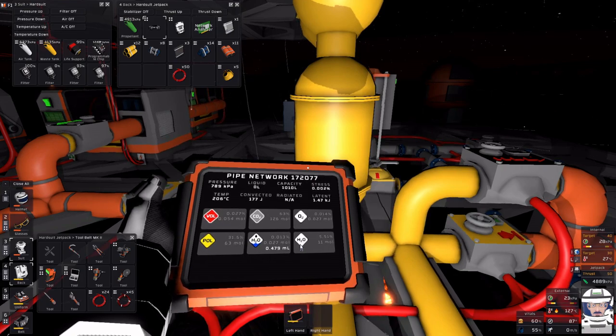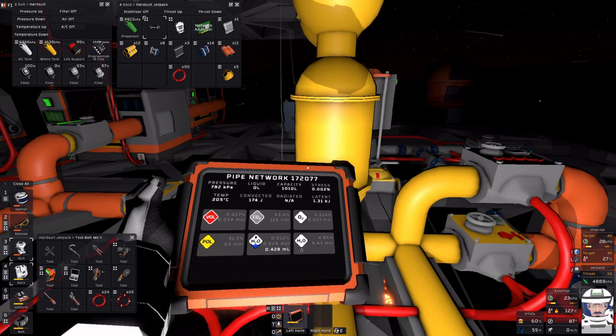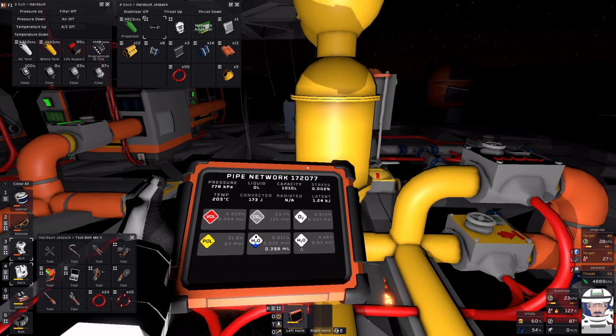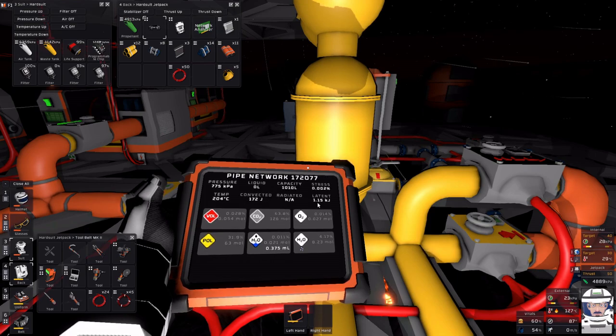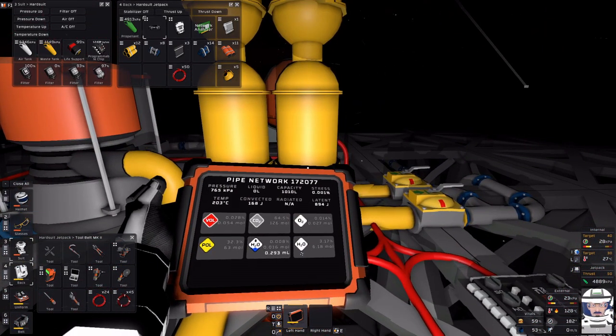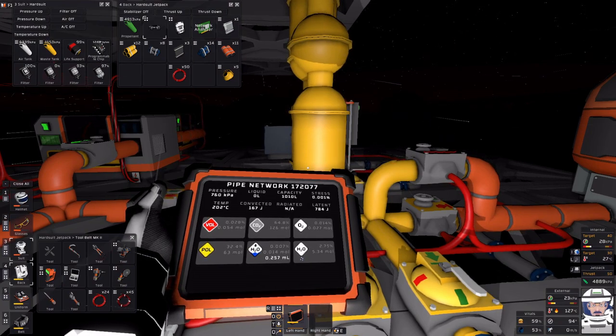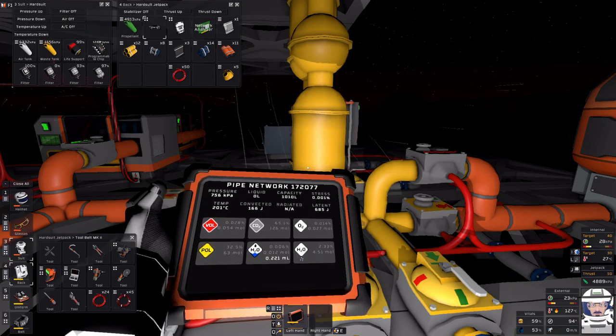Yeah, cause see, now it's condensing faster because there's a little bit more pressure. Therefore, there's more latent heat being generated. More of it is condensing. Okay. So maybe I guess what I'll do is go to 2 megapascals and let this cool down to 200.